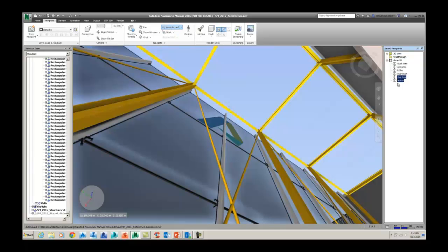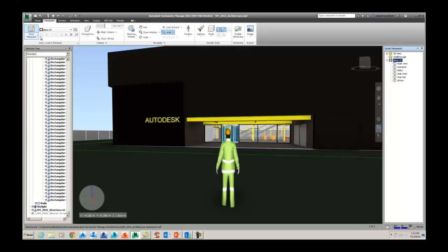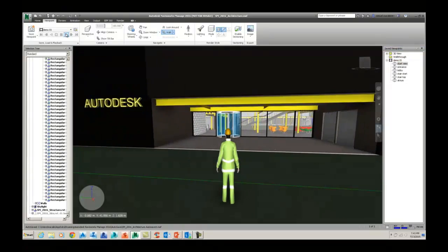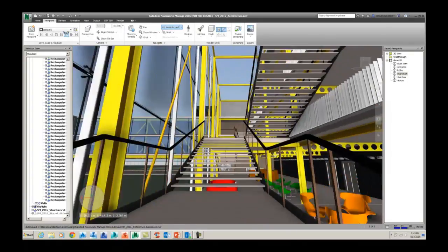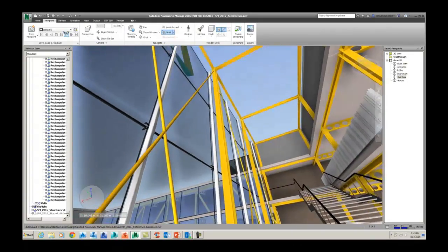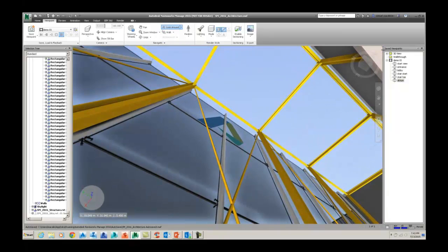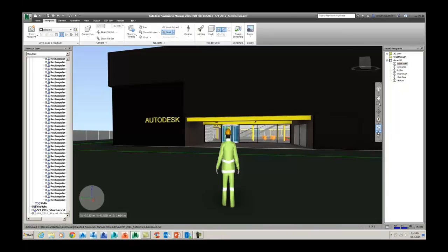We've also just here right clicked and added an animation to the Save Viewpoint, and now that's in our Viewpoint tab, and when we click and run the animation with all those Save Viewpoints dragged into the animation, we can then run through that sequence of the walkthrough.